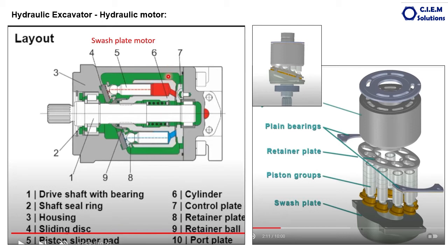Considering this is the housing, this is the pump housing, rigid one, this is the barrel housing which always moves. A set of clutch plates, that is the friction plates and reaction plates, are provided here. They are always held together with the help of the spring, meaning the brake is always in the engaged position. Whenever we want to rotate these motors, either the travel motor or swing motor, first the brake is released through hydraulic oil supply and the motor becomes free. Then the oil is supplied to these pistons to rotate the motor in the required direction.